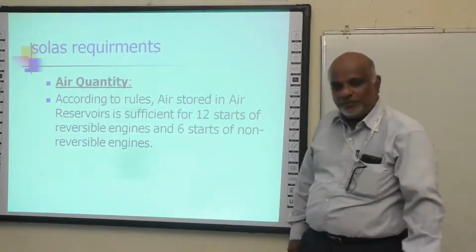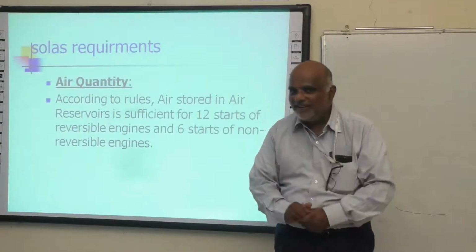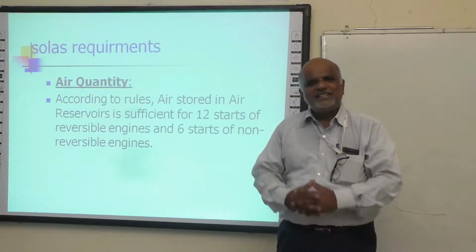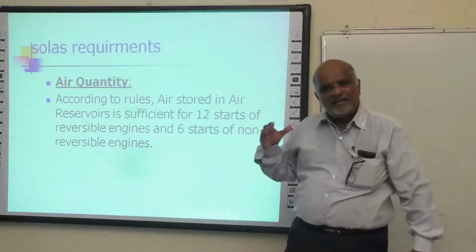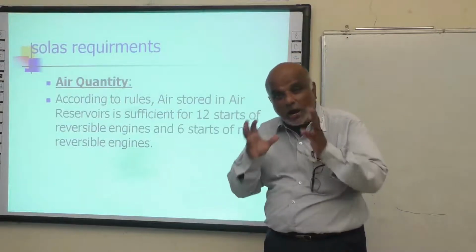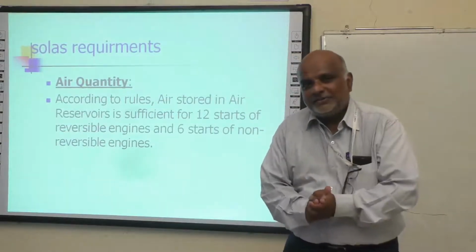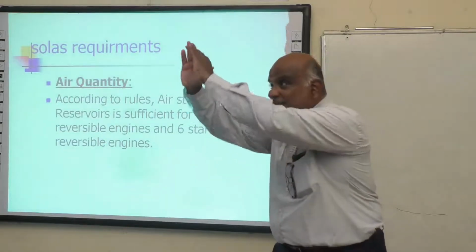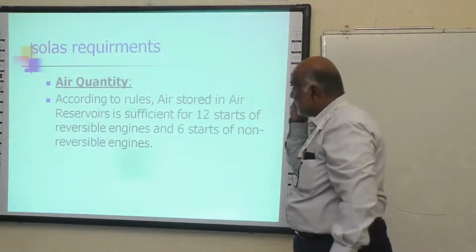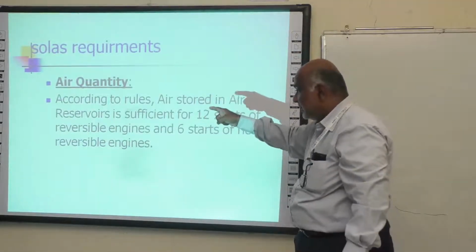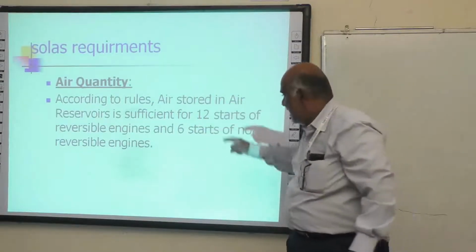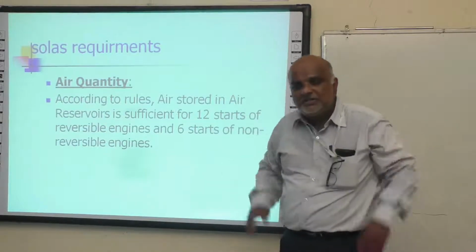Now, anywhere and everywhere, there are some regulations which are governing us. There is something called SOLAS, safety of life at sea. This regulation says how much quantity of air should be available in the air bottles. According to the rules, the air stored in air reservoirs should be sufficient for 12 starts of a reversible engine and 6 starts for a non-reversible engine.